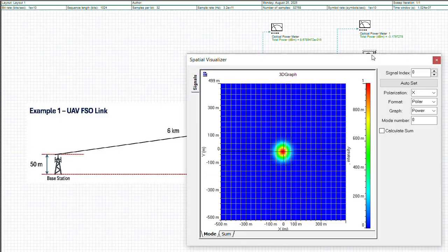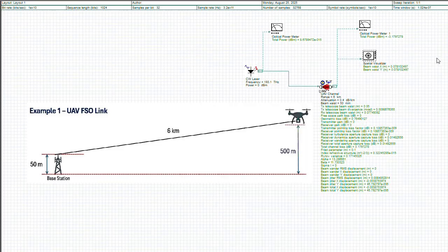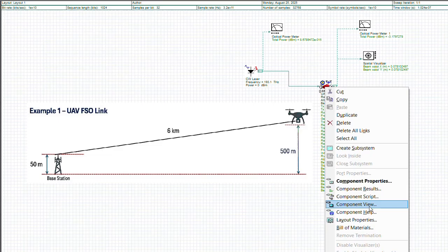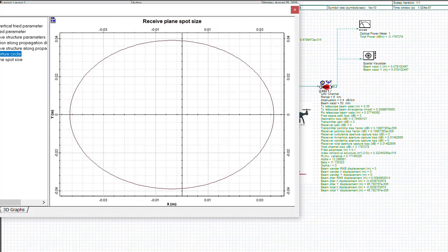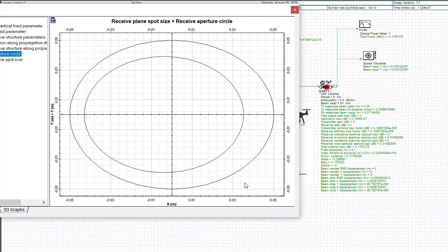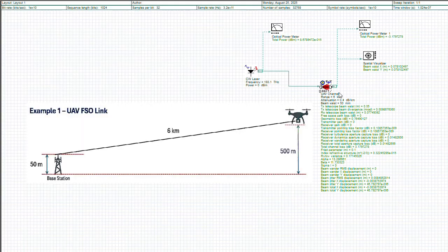If you observe the mode, you can see there's a slight shift in the mode location, and this becomes more apparent if we look at the internal view, in the 2D view. The blue is the center of the receiver aperture, and the red is the effect of the mechanical beam wandering, a very slight jitter. And there's a very slight loss here because the Gaussian beam has tails that extend outside, and you're not capturing the maxima of the Gaussian beam in this configuration.